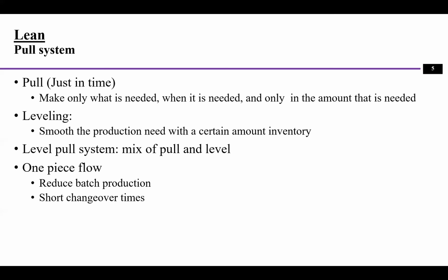If each setup time is different, or you make the setup too frequent, which means you're still going to spend a lot of time doing all the setups, and that won't make it very efficient. Well, one piece flow does not mean that every time we only make one part. In some production companies or some types of production, maybe it is feasible, but mostly one piece flow is talking about reduced batch size or shorter changeover times.